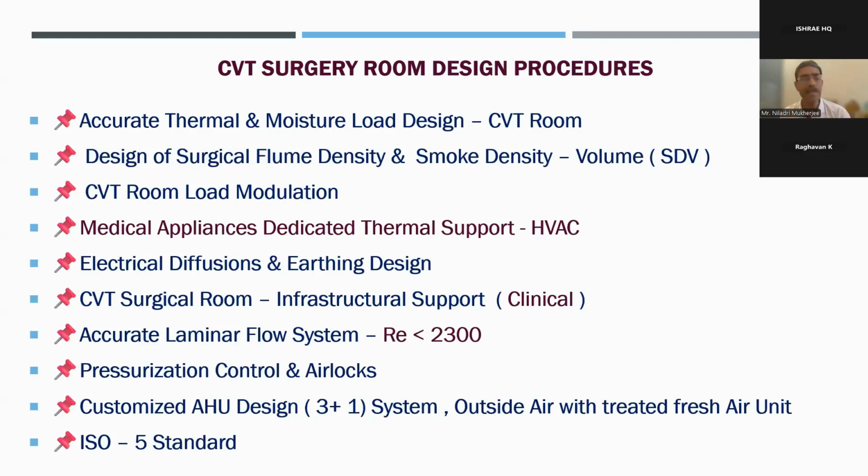And this is the design I will show you, the customized AHU design, 3+1 system. Outside air with a treated fresh air unit. It is recommended internationally, though in India, Bangladesh, Myanmar we don't find it, to use ISO 5 standard for the cardiothoracic surgery room. Just understand, a patient remains on a surgery table for 12 to 14 hours.